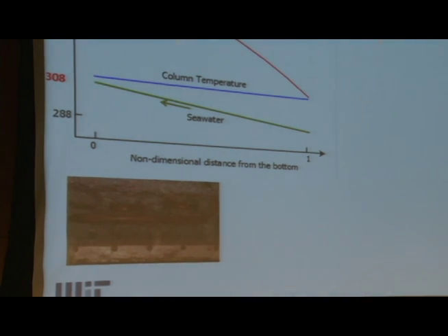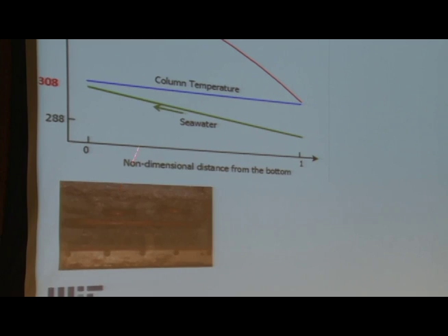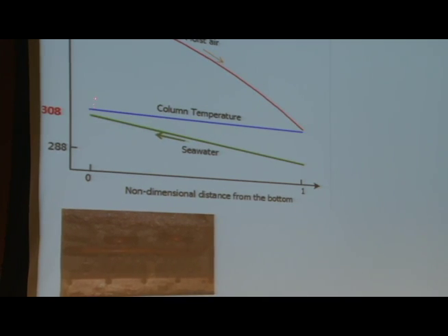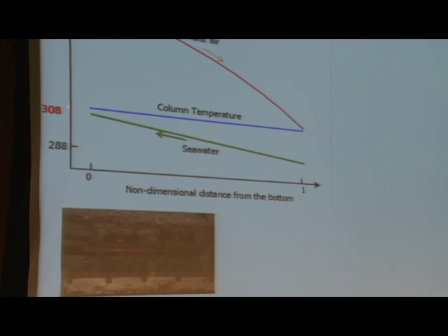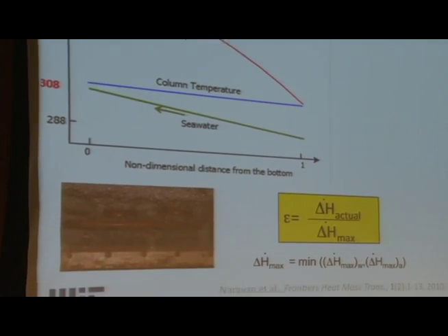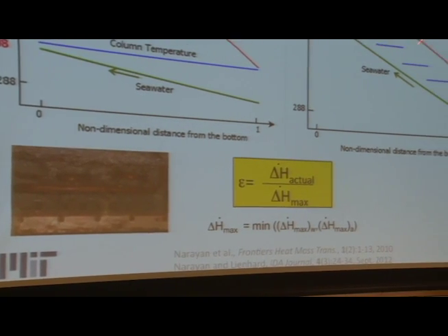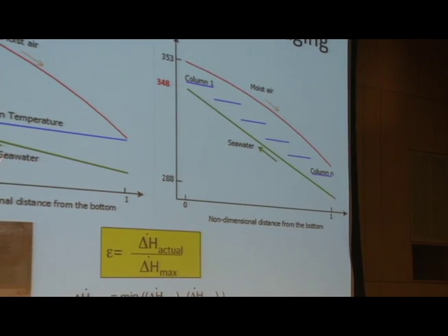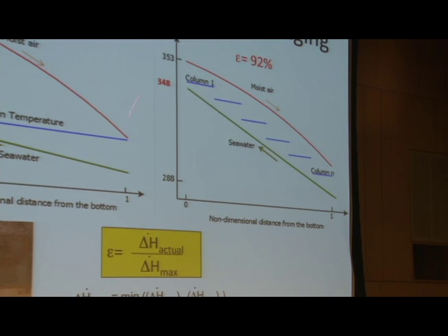I want to say a little bit more about these bubble columns. So this is what a single stage device would look like. You've got, say, seawater coming in through a coil here. You've got moist air coming in through the bubbles. They both come toward the temperature of whatever liquid's in the column. Right? That's the set point in this device. Now, you can see that I've lost an awful lot of driving potential in this process. I didn't have the opportunity to do something more efficient with just one stage. As a result, my seawater didn't get very warm. Right? On the other hand, if I use a series of these trays and go through a series of different temperatures, I can bring the seawater up bit by bit through each of several stages, with the result that instead of having a device that's 30% efficient, I have a device that's 92% efficient.